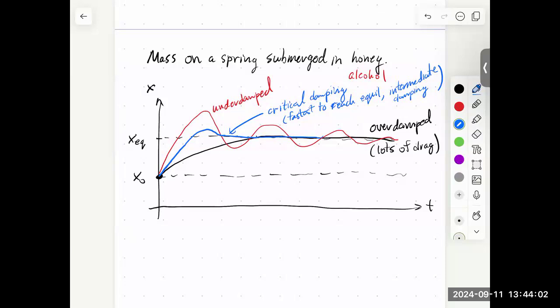Yeah. Is there a term for instead of drag, but like acceleration in the direction of the current? An acceleration in the direction of the current. So that instead of damping, oh, like you want a growth in the oscillations? Yeah. So if you wanted to do that, you're going to have to inject energy into your system. So you're going to have to drive it with something like a function generator. So you can do that, but not with just a battery.